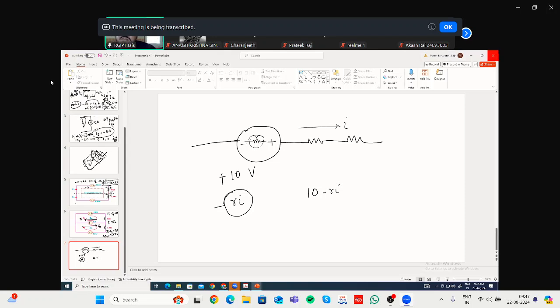Let us say you go to the market to buy a battery, a pencil battery, 5 volt. You ask, give me a battery of 5. But because of this small finite resistance, actually the voltage will be far less, and that will also be dependent on current. If you are drawing a huge amount of current, let us say 10 amperes, r is very small but I is very high, then ri will also be very high. That means we will not be able to get any kind of voltage.